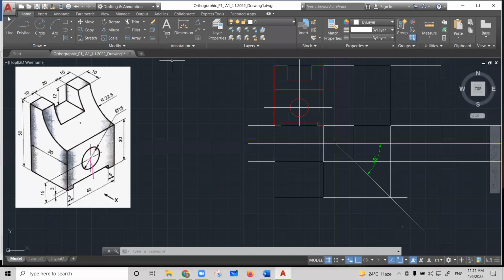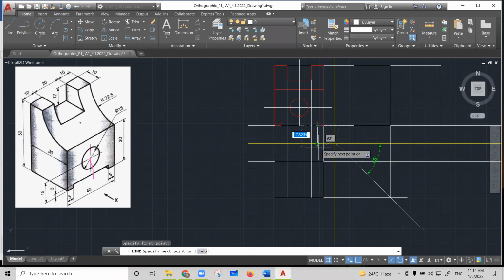Now you have to think about getting your top view. Okay, so for top view, do one thing. First of all, take the projections from this line. Each point initially, because as you are a beginner, if you take projections from each point from your front view to top view, even though throughout its width, no problem. You can take the projection from this also. Even though you can take the projection from the circle itself, we'll think on this later on.